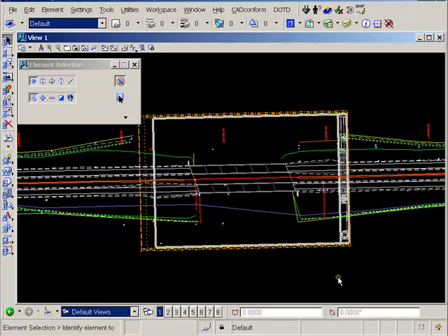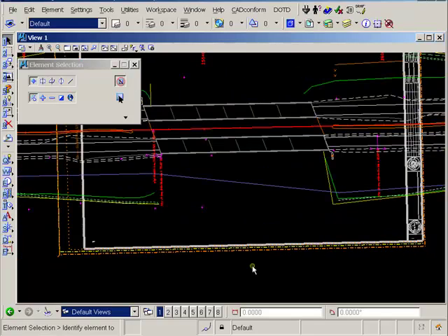Now I will use the zoom out command to view the entire border graphics in my current view. I personally don't like to work in a rotated view, so I want to straighten out the view orientation so the border appears at an angle of 0 degrees. To do this, I want to use the border to rotate the view dynamically.